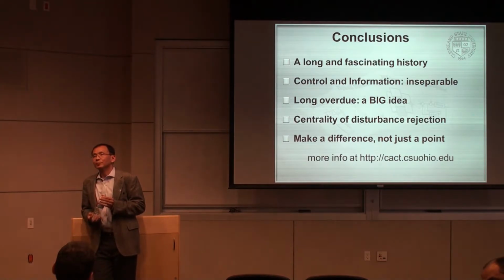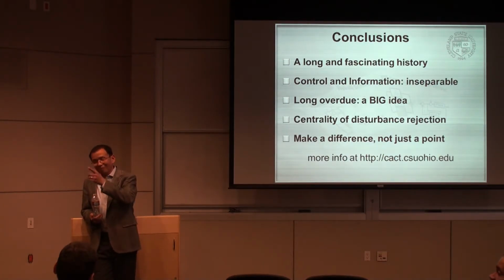So you still need some plant model, and it needs to be parametric, and then you'll basically do an active online estimation of that, assume that that's true, and then hope that all the parametric variation, if the plant parameters change, you still have enough wiggle room to do active online estimation in that parametric framework for your plant model. The strength of this is that you can adapt to changes in your plant model because you're simultaneously estimating the model and the disturbance jointly as just a general disturbance. And then you're fitting it to that.